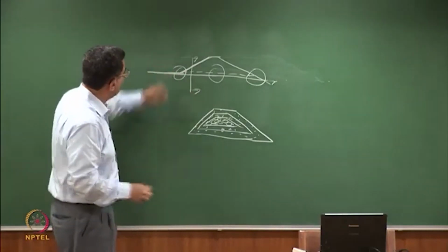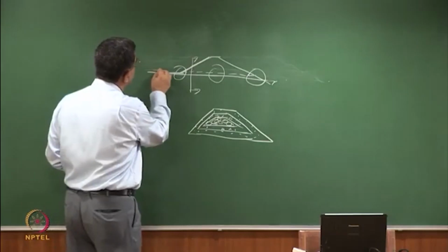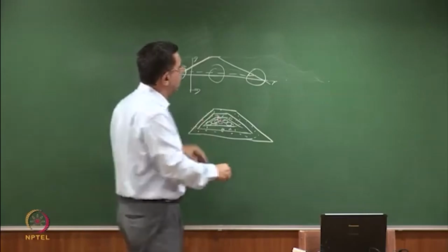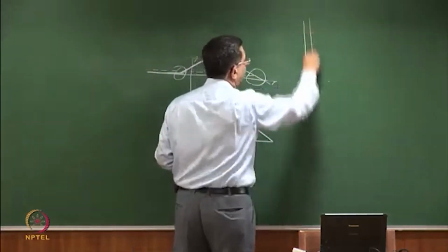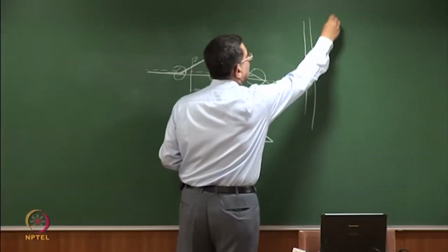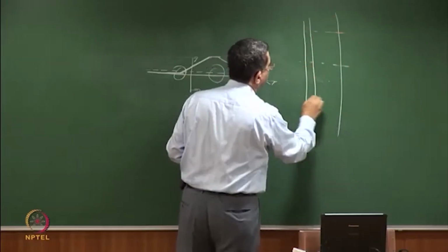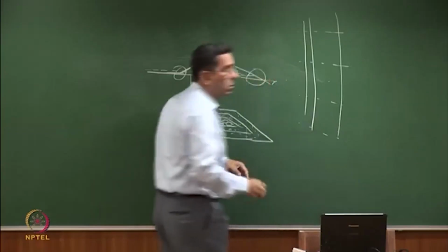You have a sand layer at the bottom. I've already told you that will have to be interconnected to this drain, so that within the embankment, if I'm now looking at this embankment from the top, that's the crest, that's the downstream toe. At certain locations, these drains are coming through to allow the water to drain out.